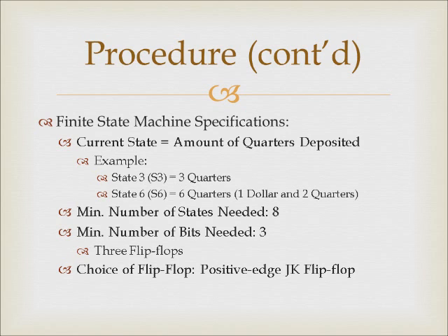It was realized that these 8 states could be represented by 3 bits and consequently 3 flip-flops. The team had initially decided to implement D flip-flops, but came to realize that it would be more advantageous to instead utilize JK flip-flops.